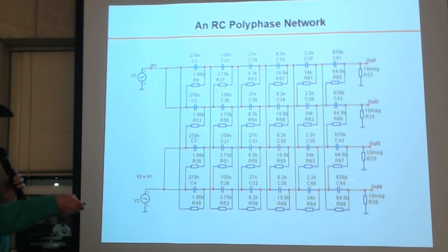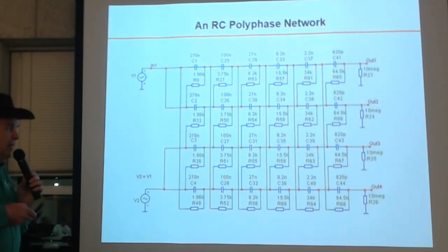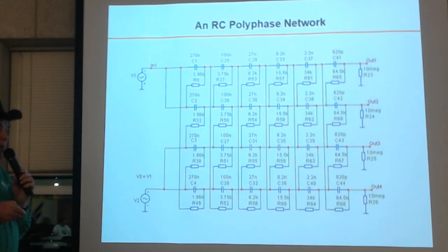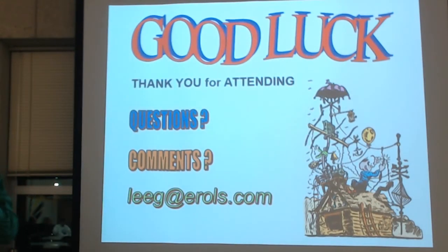And you can go and run them the opposite way back for the receive. And they'll combine them back into a differential pair. So that's what the polyphase network is about. So that's kind of the neat way of generating SSB that is not that widely used yet, but I think, as I said, it's also something which can be done probably in digital implementations as well. So that's about it. So now, anybody have any questions?